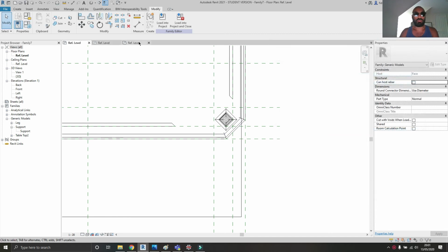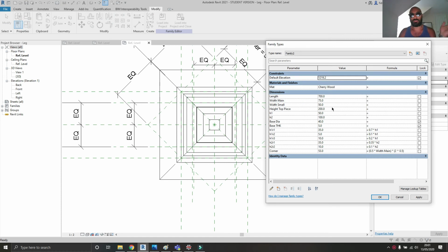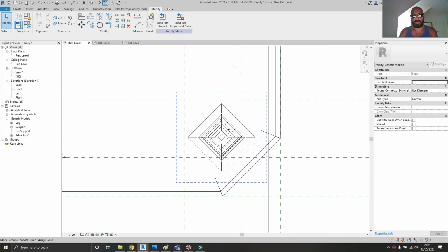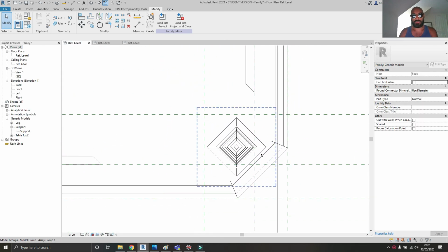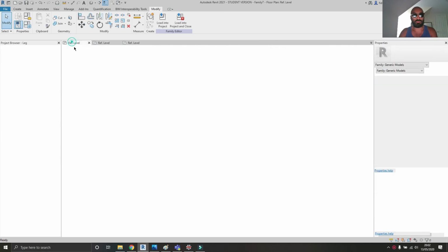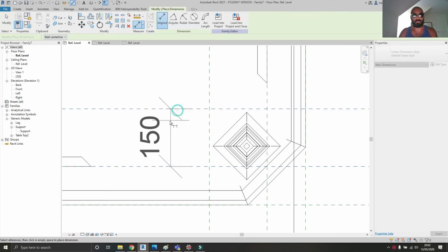See, in this other one, in the leg itself, it had a different name. The name I gave it at the time until I realized. So I gave it width main. But generally, we're going to do the exact same thing here. We're going to give the distance between this and that the same Pythagoras Theorem equation. So I'm going to come here and I'm going to copy that. Control C, doesn't let you right click. DI for dimension, there to there.